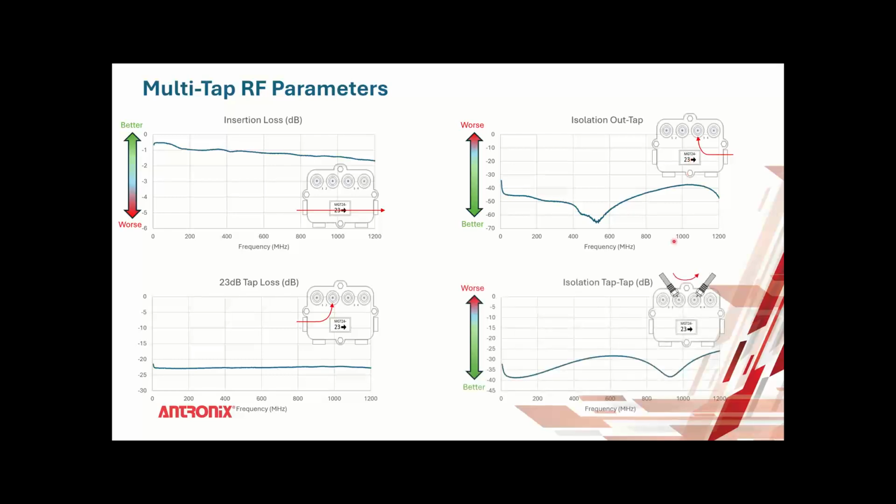If I may, Neil, I'd just like to emphasize that the isolation becomes ever more important as the bandwidth of the return widens. When you have like 500 megahertz of return bandwidth, if you have poor isolation, it will actually interfere with the other customers on those same tap ports. So making sure you have the right cable simulator or attenuator in the tap becomes very important.